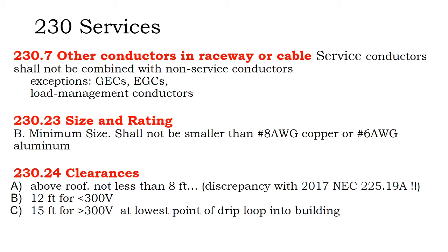Clearances, above the roof, not less than 8 feet. Well, code just said not less than 8.5 feet. It's a discrepancy in code. It happens from time to time. 15 feet for over 300 volts.